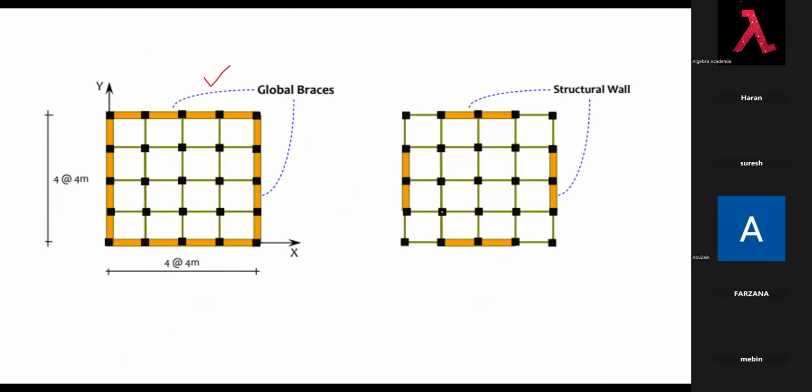suppose you take this column, all this load will come to this column. So the axial load to this column in case of shear wall system is going to be high. It is the same here also. It all will come here only. But we are just showing this frame part. So here this column will have maximum load.